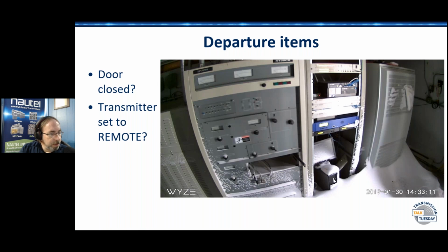Yeah. Somebody had mentioned airflow interlocks, and that is a really good point about airflow interlocks on older transmitters. He suggested that we should add them on ours, but we actually do temperature monitoring throughout, so it's less of an issue on the newer boxes. However, it certainly is another one of these things that should be inspected. Somebody posted on Facebook not too long ago about a transmitter with the interlock literally duct taped over, and we started off with safety, but that's something that I really don't like to see.